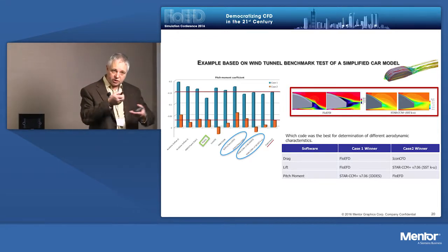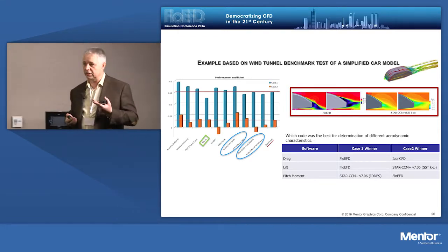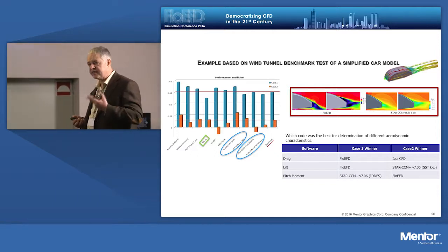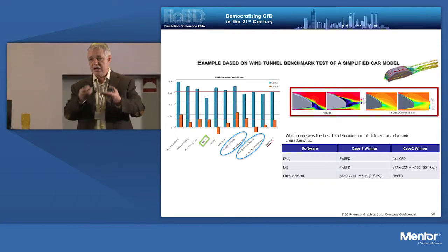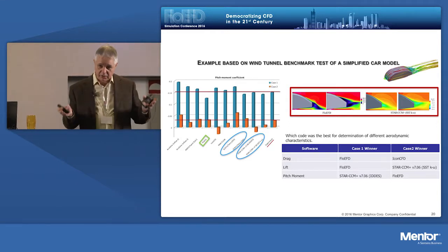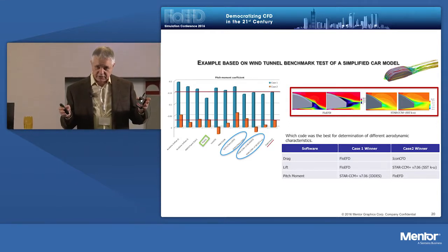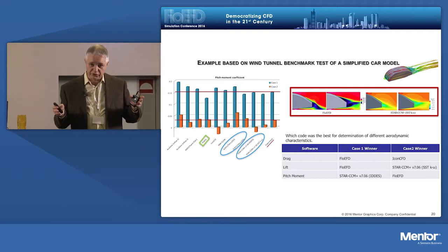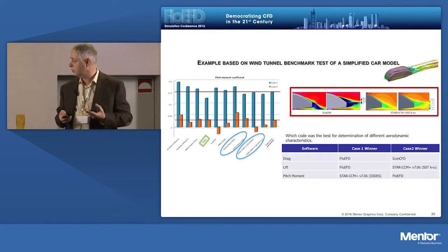So the user selects what turbulence model to use. We took the same approach: the K-epsilon model in the core flow and our semi-analytical approach in the boundary layer, which is in fact a combination of a lot of turbulence models.